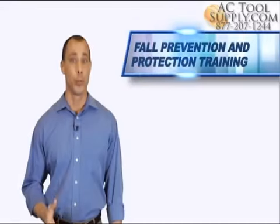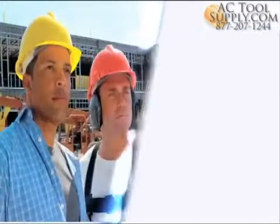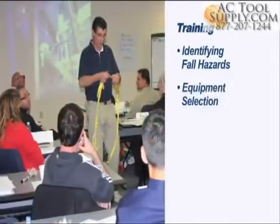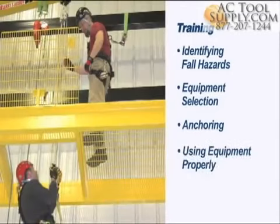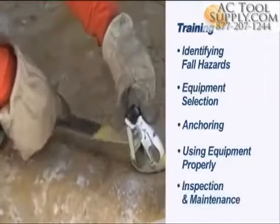Every worker must be trained in the proper use of appropriate fall prevention or personal protection equipment. Training should include identifying fall hazards, selecting appropriate equipment, following proper anchoring procedures, and using equipment properly. Workers should also learn how to inspect and maintain equipment.